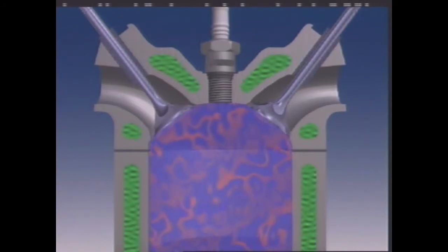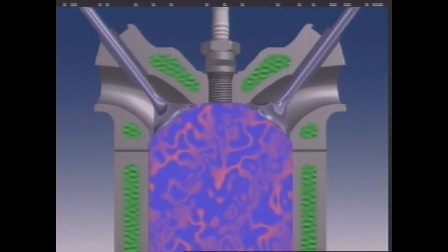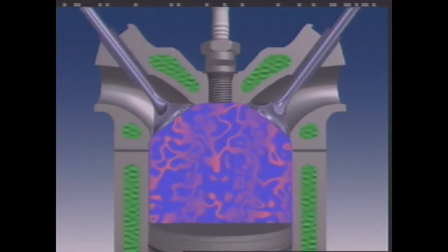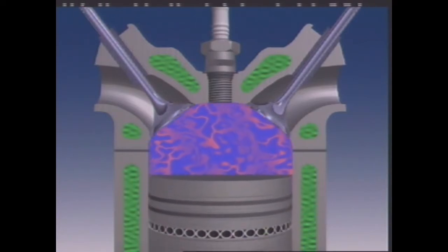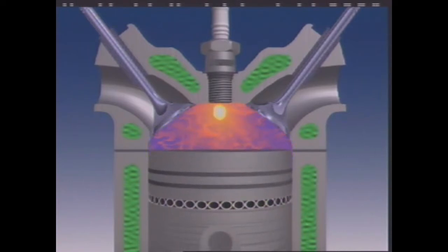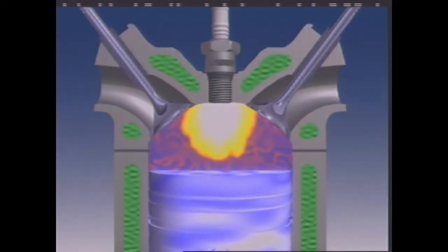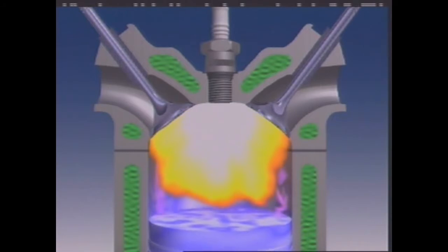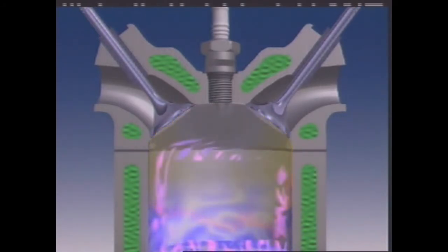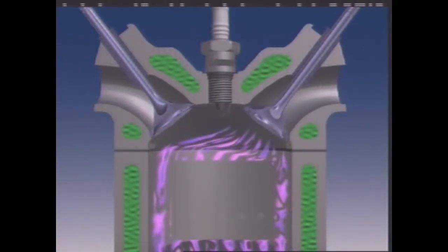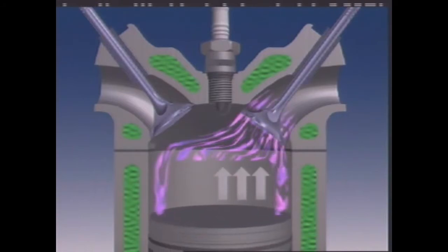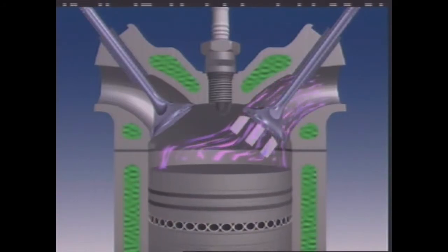When combustion occurs in the cylinder, the walls, piston, and piston rings are slightly cooler than points closer to the burning mixture. Some of the air and fuel molecules come in contact with these cooler parts, and they cool down until their temperature becomes too low for combustion to occur. They are left unburned, and when the exhaust port opens, they leave the cylinder.